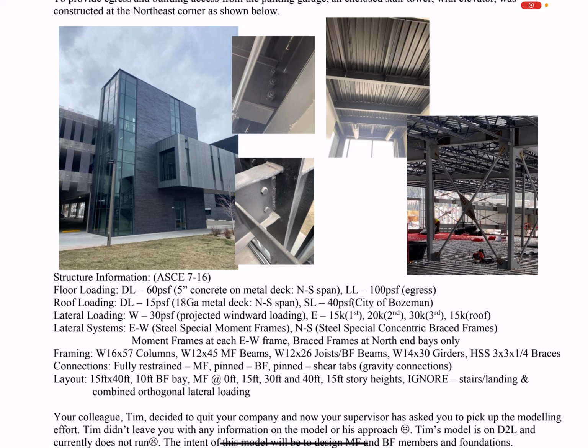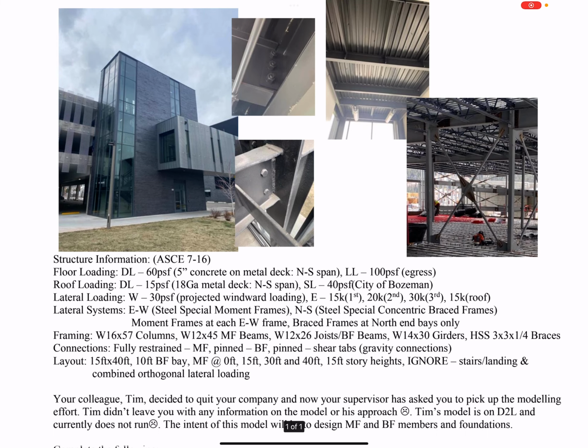Dead load is 15 pounds per square foot. It also spans north-south. The snow load's 40 pounds per square foot. Okay, that's roof snow load, right? That's dictated by the city of Bozeman.